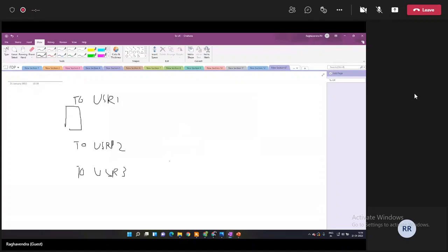Let's say I'm doing some sort of music algorithm to determine direction of arrival or whatever. Let's say I have to work with 3 USRP RIOs at this point of time. Now, in the software, I can say turn on USRP RIO, all 3 of them at a time. The advantage with LabVIEW software is that you can actually implement a good amount of parallelism in your code. You can have two portions of a code running simultaneously without interfering with each other.